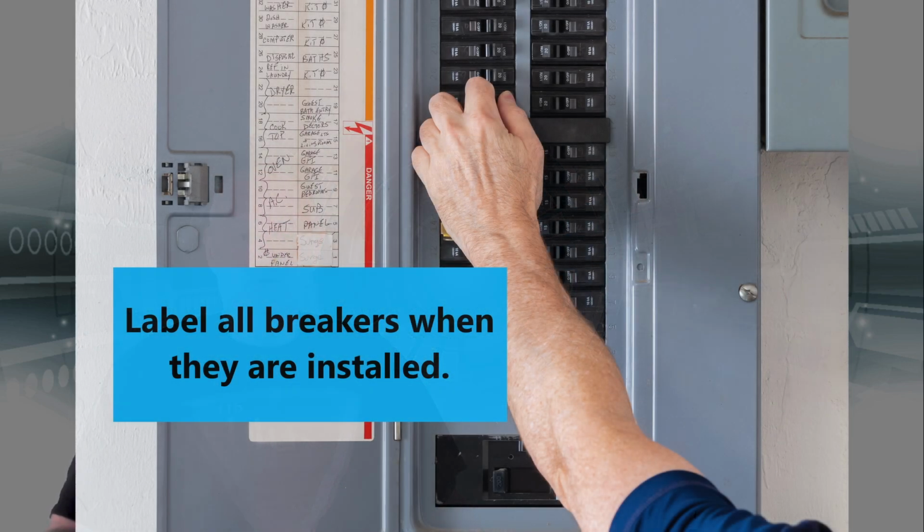The incoming power in your house can vary from 110 up to 125 volts. It depends on the day and the load. The power company tries its best to regulate it at a constant voltage, but it honestly isn't. It changes. Now, when you do work in a breaker box, always be sure to put labels on all of the breakers. That way you're not confused later. If you have an emergency, it is easy to see which breaker you need to turn off.